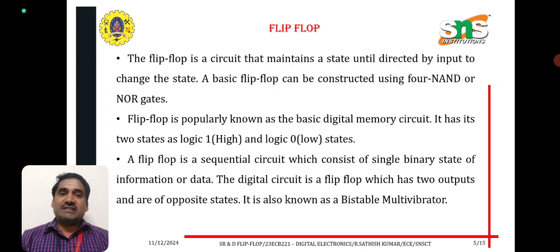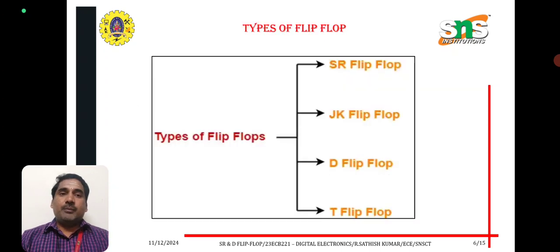A flip-flop is a sequential circuit which stores a single binary state of information or data. It is a digital circuit which has two outputs that are of opposite states. It is also known as a bistable multivibrator. Types of flip-flops are SR flip-flop, JK flip-flop, D flip-flop and T flip-flop.